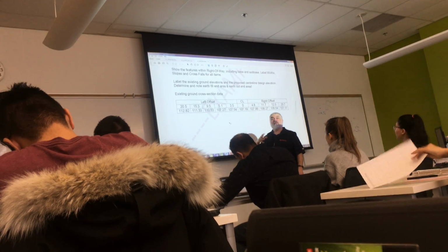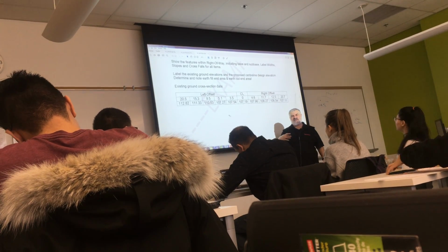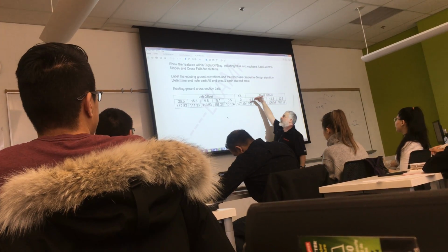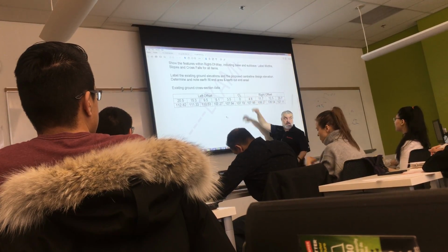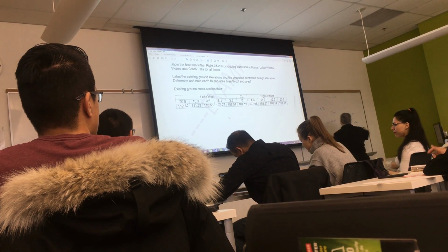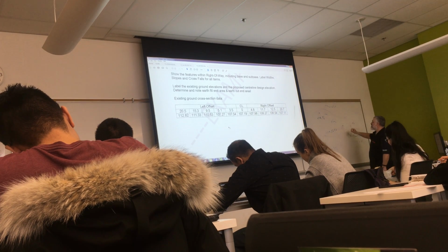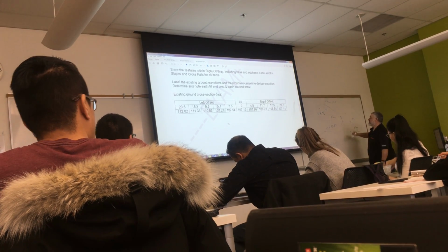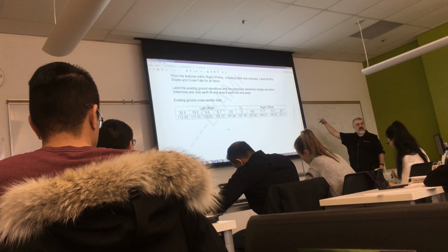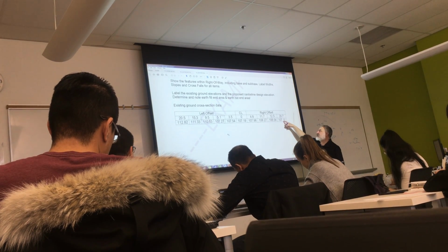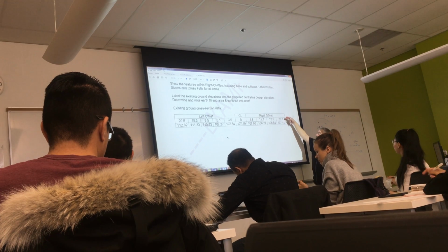Okay? To plot this in AutoCAD, this is the engineering discussion. To use AutoCAD to draw this, think of the top line as the x coordinate, right? The offset. The offset is in this direction, that's the x coordinate, and the elevation is in this direction, that's the y coordinate. So the top row is x, the bottom row is corresponding y. So this is the point 20.7, 107.11, x and y.